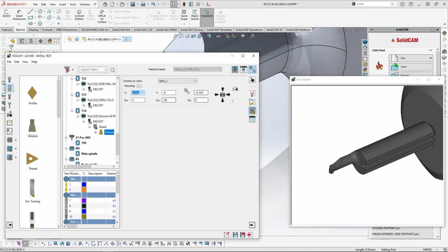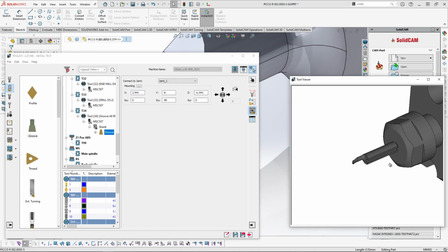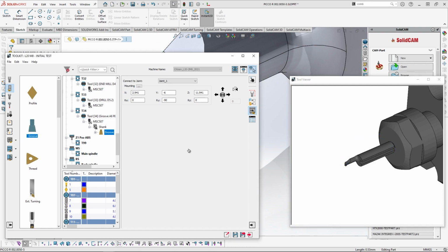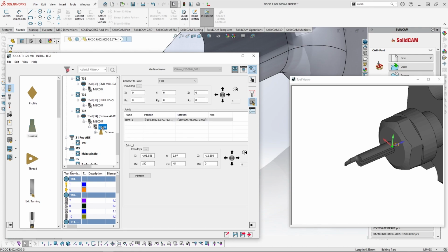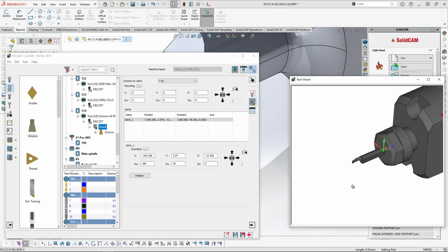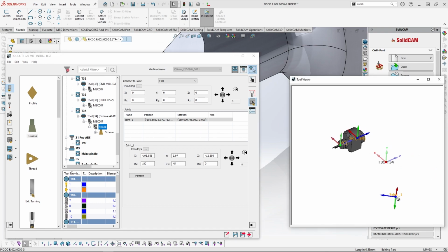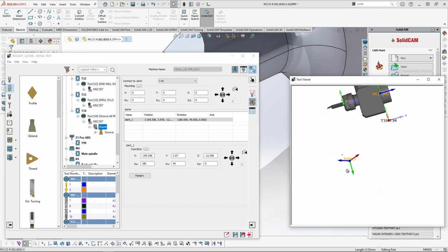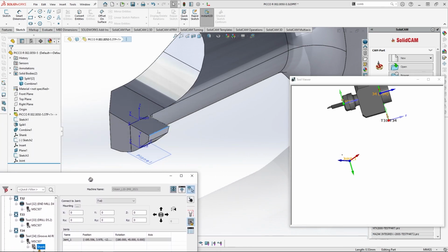But before doing that, we need to set up our joint. Where is our joint with respect to our shank? Where we would like to put our insert. It's here, right? So how to do that? I'll just go to the shank, and here we have this joint. Where it is located, we don't know. Here it is, some very strange position. So we create our coordinate system over here.